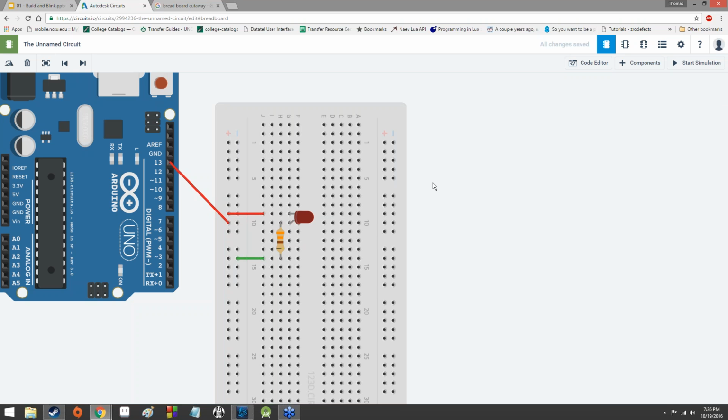There's no particular reason why I need to do that, but it's good form because when you're working with circuits, red generally means a hot wire, whereas black generally means a ground wire. And this is something that's basically a standard, certainly for electronics. You're going to see this in houses as well, except the colors are going to be all messed up. White is going to be your hot wire, and depending upon how old your house is, I believe either green or black is going to be your ground wire.